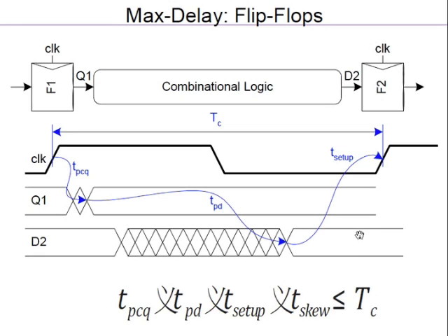You see there is so much margin here. You are being inefficient with power consumption because you are running it at much higher voltage than what it needed to run, but it will run correctly. So can you be greedy? Can you make it run at the voltage where you just meet timing? That is the lowest voltage for you to run, which will be the most energy and power efficient. If you have to reduce the voltage some more, it will fail. If you increase the voltage, it works fine, but you are just wasting power.